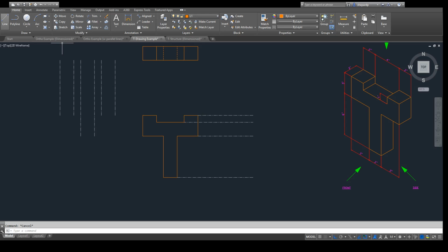Well, we're going to go back into L1, and again, we're starting with our depth here. So I know that it is 2 inches deep. It is 2 inches wide at this point. Now I'm going to go up. I see that my total distance is 9 inches, which should match up with our projection lines here, which it does. Again, another 2 inches, and I go down 9 inches. I think this is the easiest way to start the construction of it. I have these 4 lines right here, which is the total outside shape as indicated right here. There's my rectangle that I just drew.